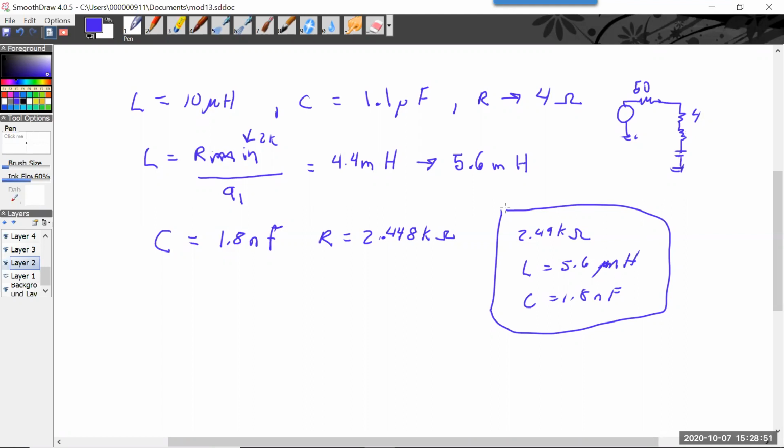And then you could put it in LTspice and simulate it. What would be great about LTspice is that you can vary these parameters, because when you buy parts, there's a variance, a tolerance. I could do a Bode plot, and this is the magnitude if everything is exactly what it's supposed to be. But there'll be things shifted one way and then shifted the other way. I'm exaggerating a little bit based on the tolerance.